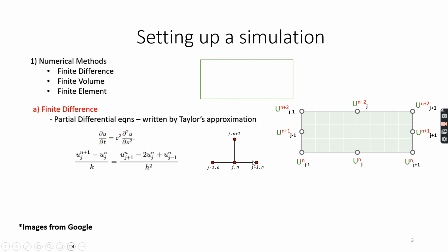So basically, if we apply the finite difference principle over here, as you can see, j is taken to be the space and n is taken to be the time step. At this particular time step of n we advance through space, and for going through the next time step we go for n plus 1 at the same location of space, and for the next time step of n plus 2 we advance, we are in the space of j minus 1, j and j plus 1.